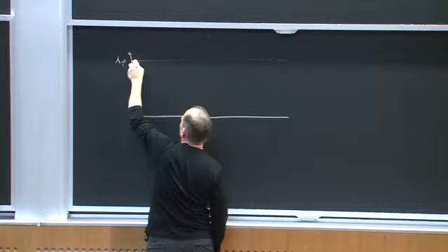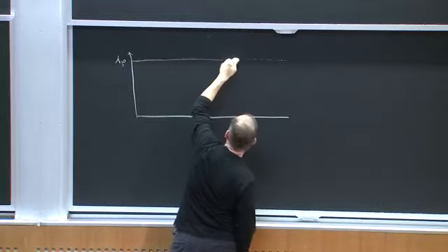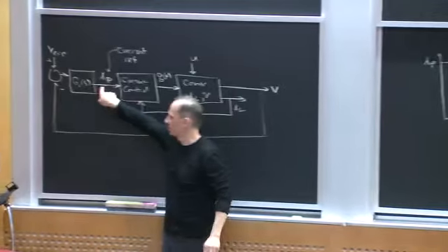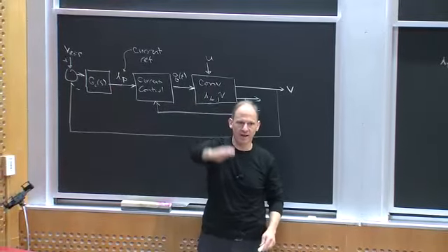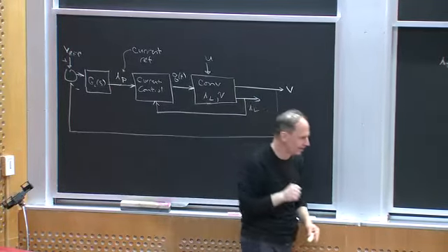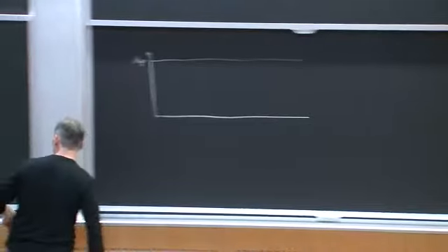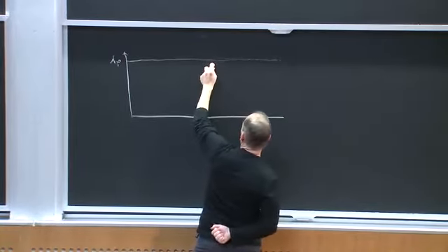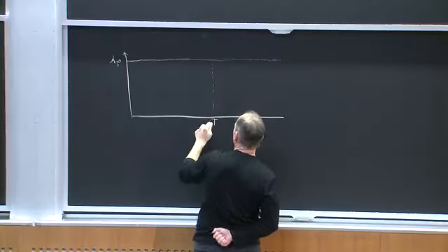Within a switching cycle, this is more or less a constant defined by this compensator, but it's going to move up and down as my outer loop tells it to. Then I'm going to create a slight variation off that, and we'll explain why a little bit later. But suppose this is my switching period T.